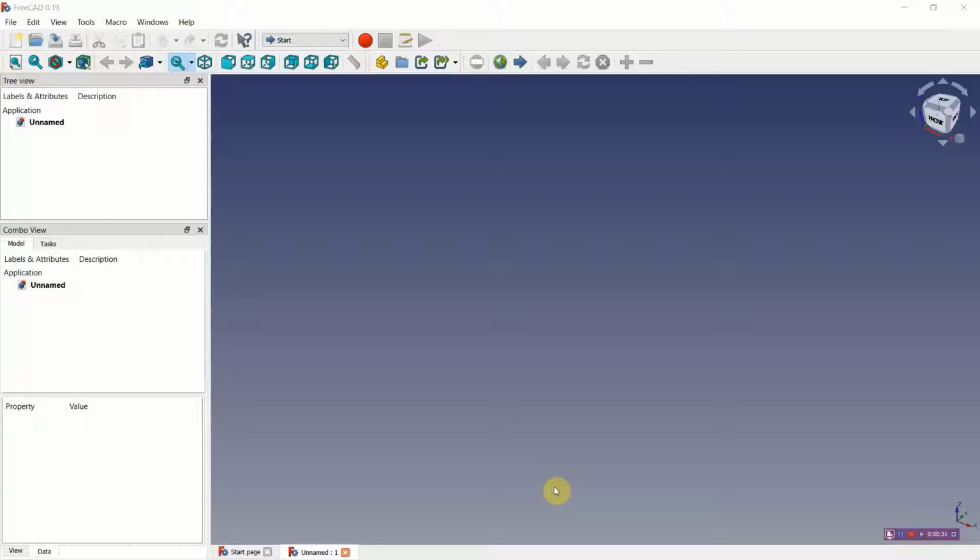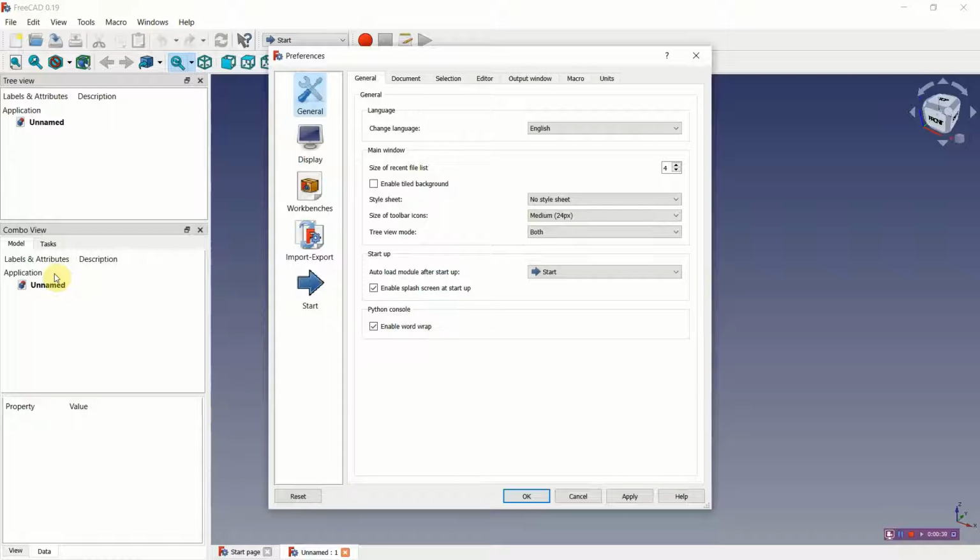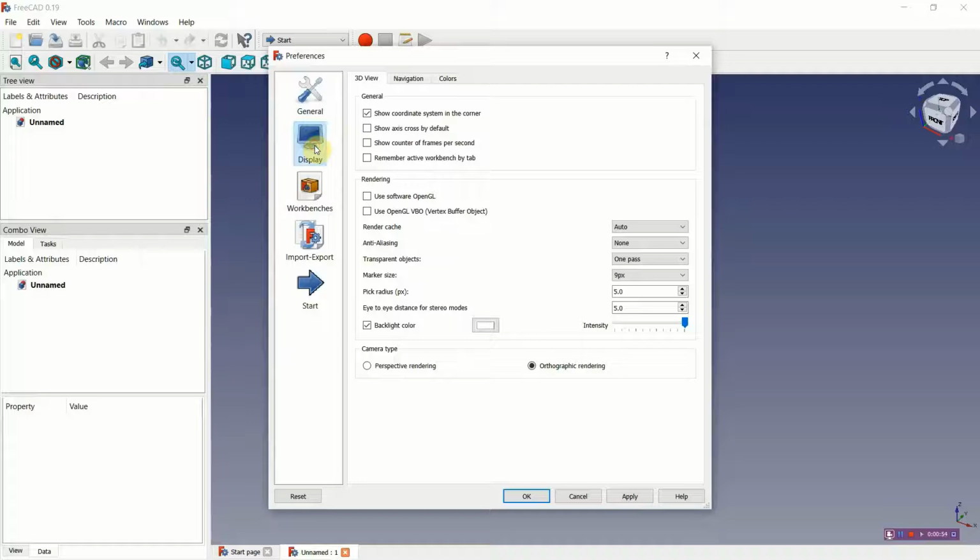The first thing I'd like to explain, I think, is some of the viewing options. If we go under Edit, Preferences, you will find certain so-called workbenches shown here, and viewing options. And for each of these, we can change certain information like the background colors or line thicknesses and so on. And once we activate other workbenches, which I will be showing, then more items appear down here.